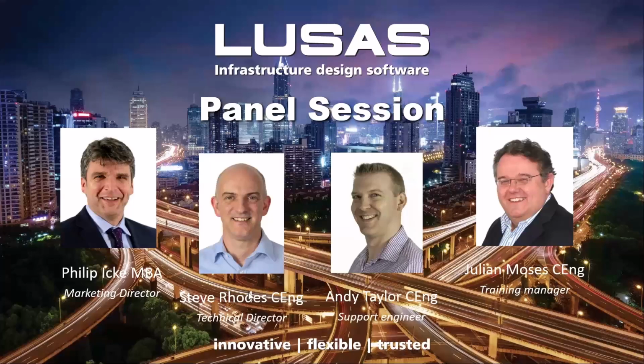This particular facility that I was showing is more for where you've got more complicated situations where you can't use that sort of simple analysis. So maybe a concrete hinge, as shown in that 2D image at the end of my demonstration. That 2D concrete hinge you can't really cover with basic code capacities. So doing the finite element analysis using the embedded reinforcement is the way to go. I suppose the other thing, Andy, is things like deep sections where it just doesn't really correspond very well to a beam analogy for doing a frame. Yeah, so when your beam analogy falls down when you're looking into deep sections, then again, that facility is very useful.